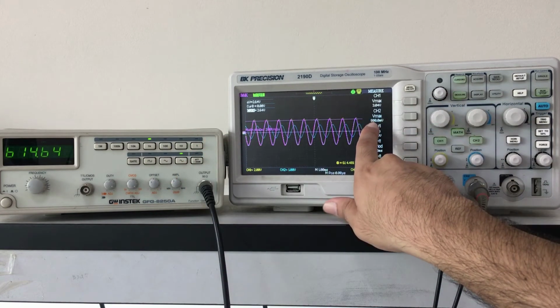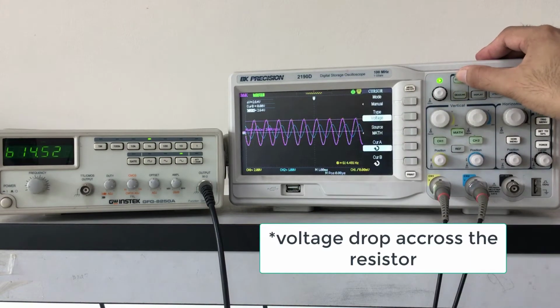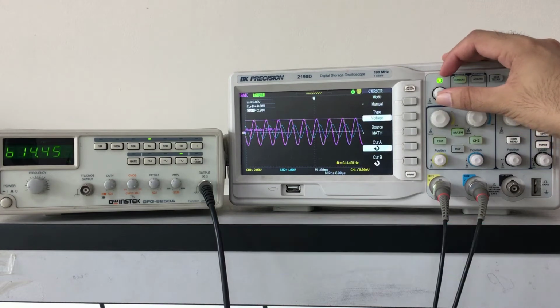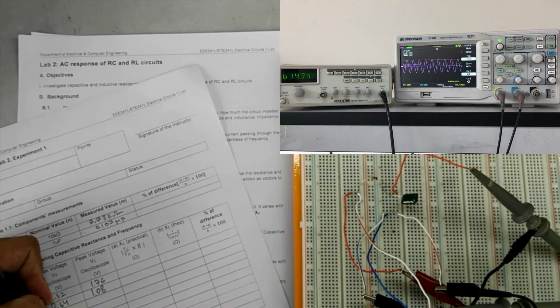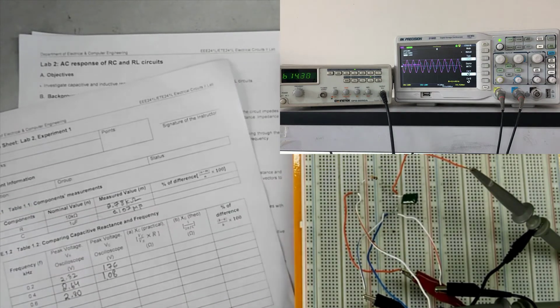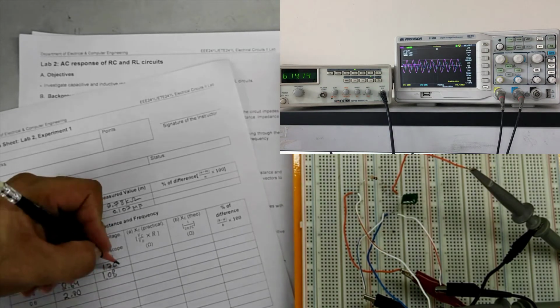Now channel 2 Vmax is 800 millivolt, and the voltage drop across the resistor is 2.8 volt. So 2.8 volt for the resistor and 800 millivolt for the capacitor.